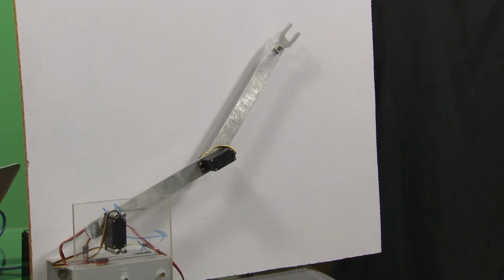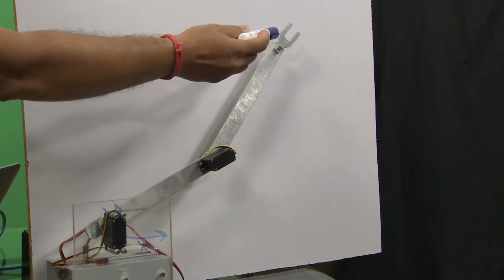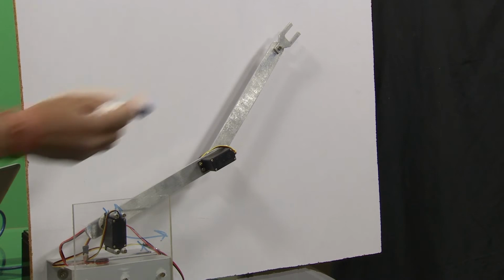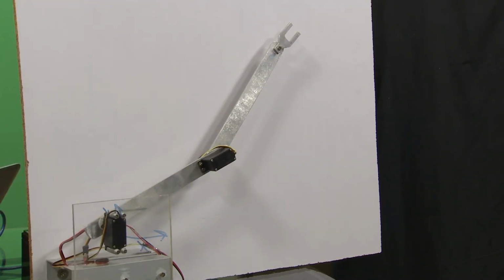Now how do I know that? Essentially we need to assign axes at each of the frames and then find the relationship between this frame and then this frame, and this frame with respect to the base frame. So what this basically boils down to is that we need to know the frame to frame rotations. If you look at the frame to frame rotations and translations, there are two operations that go on. One is a rotation, the other is a translation.